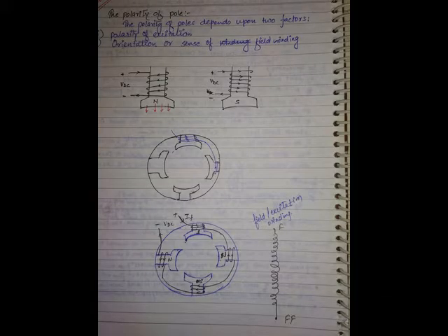Inside the machine, between the stator, meaning this entire part, and the rotor, the rotating part, there is an air gap. So as the pole spreads, automatically the air gap will be reduced. I have told you the significance of the air gap in a simple diagram. As the air gap increases, the MMF requirement automatically increases.